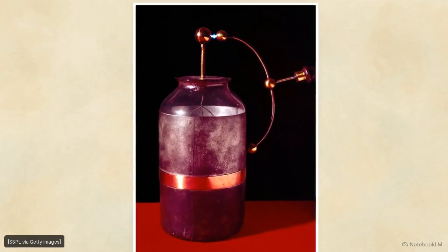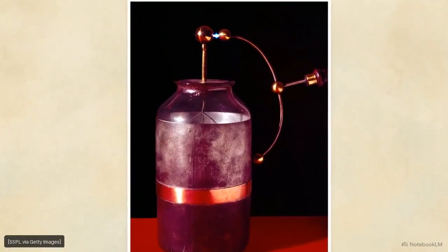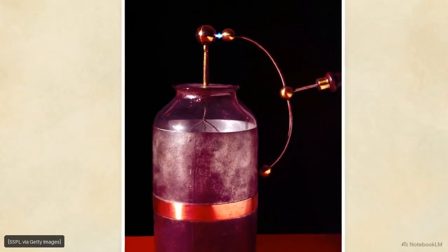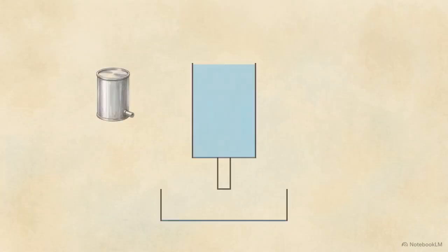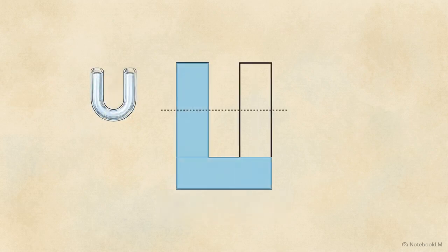Early electricians stored this immense charge in a device called a Leyden jar, which acts as an electrical condenser or capacitor. When a capacitor discharges, logic suggests the electricity should simply flow from the high-pressure side to the low-pressure side until the voltage reaches zero and then stop. Instead, the current overshoots the 0 point. It empties the capacitor entirely and continues forward, reversing direction and sloshing back and forth in a rapid oscillation.